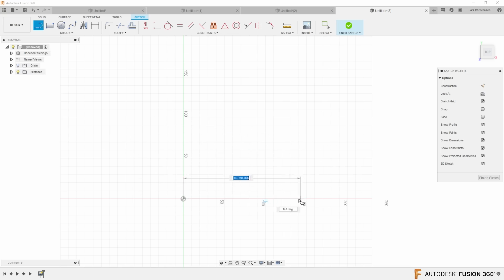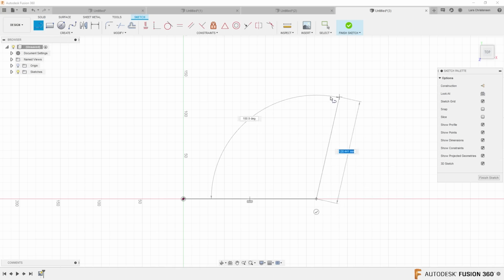Now if I go over here and let it create that horizontal one, I'm just going to left click once, and you will see that icon appears right there. So now that is horizontal. If I move up where it becomes vertical again, you will see down at the bottom it makes a little rectangle where those two lines intersect. That would make it a perpendicular relationship. But I'm just going to let it be out at an angle here. Left click once, left click again somewhere out here.